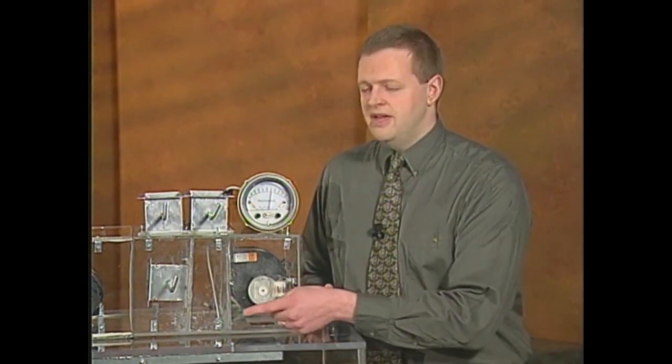Again, proper location and selection of the indoor and outdoor pressure sensors is critical. Plus, since this return air plenum is generally pretty small and turbulent, it may be difficult to properly locate that sensor as well. Next, Dennis is going to share an approach that may be able to eliminate that particular concern. One approach that may avoid the return air plenum pressure sensing problem is what we call optimized damper control. It can improve control stability and reduce fan horsepower a little bit in the process.